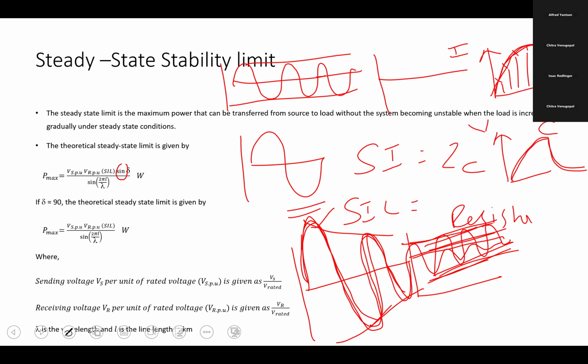Then you can do all the calculations. Your propagation time constant, the angle calculation, everything can tell you how long it's going to take to stabilize. Based on that, you can allow your protection devices to work. The protection device will not trip the circuit until that time has passed, if the current is within that peak value window. If the peak is within that window and it takes more time to settle down, then it is a fault current.